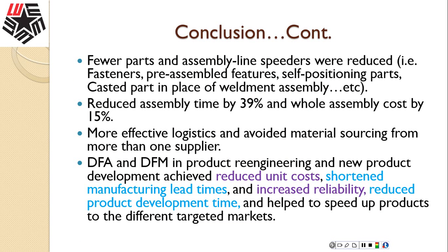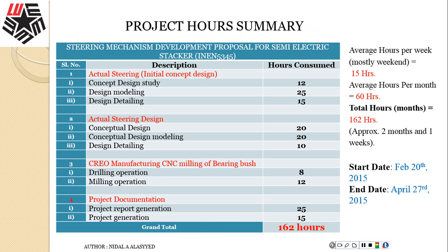One of the reasons that people usually go for design for manufacturing and assembly is that sometimes they look at a part that exists in the market and they want to re-engineer it. So we do some re-engineering in order to fulfill some company requirements. For example, this stacker was originally created by a very good Chinese company, but the design in the Chinese company is not really accounting for much safety. Usually the safety factor doesn't go more than 0.9 or 1.0, compared to 2.0 in our design, and that was also part of the assumptions made in the calculations.